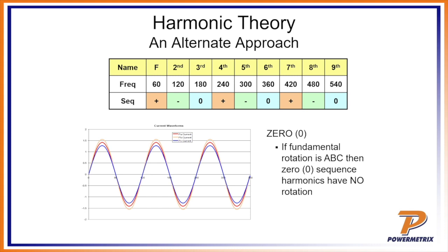Now the problem with that, in the real world, is that on, say, a 4-wire Y, we have a voltage and we have a neutral. Ideally, the return current is supposed to go back through the neutral. Now these zero sequence currents are going to start going back through your ground conductor. A lot of times, the ground conductor in a system is not sized appropriately in terms of wire size. So if you get too much current flowing through, it can cause a lot of heat. In the worst case, it can cause a fire.